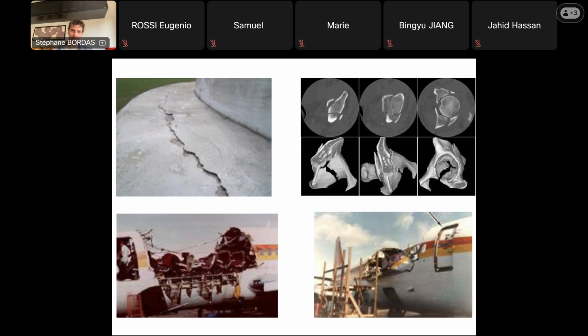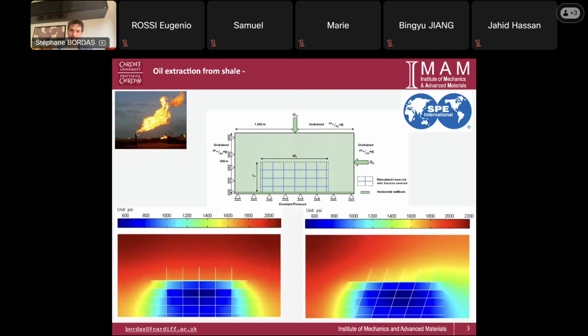Here is the sort of very fashionable convertible aircraft. That's a Comet. This is a type of aircraft that had square windows, and the square windows led to stress concentration. The stress concentration led to cracks, and because all the windows had square angles, the cracks connected to each other and then eventually broke the whole fuselage, which led to this very beautiful, fashionable convertible. You also have to deal with that with reservoirs.